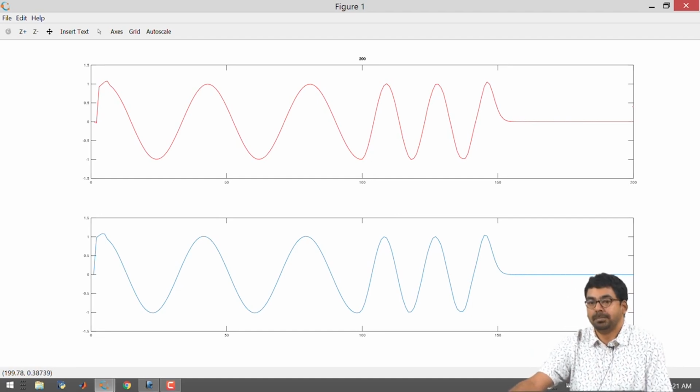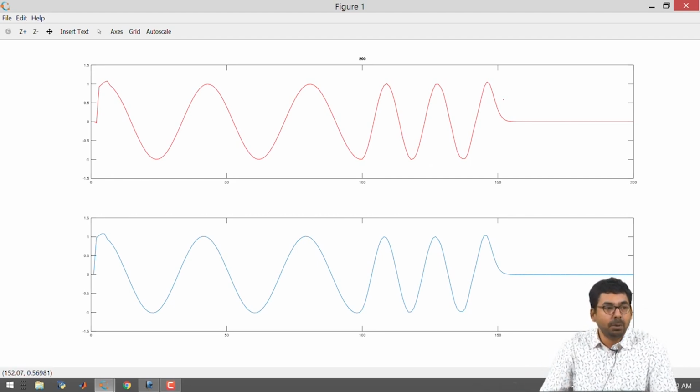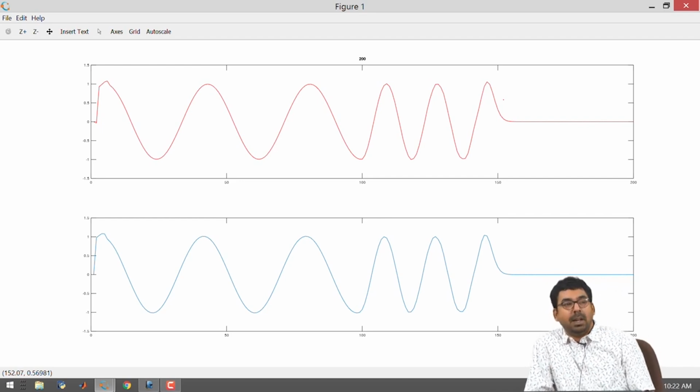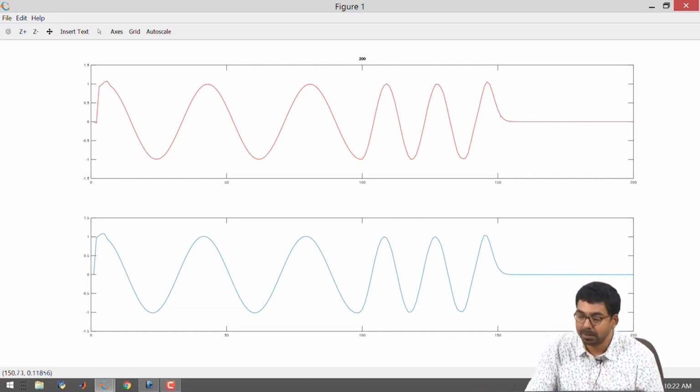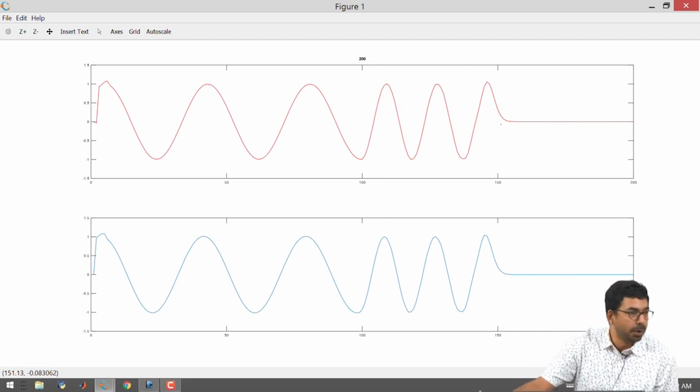It did not do that, simply because we already know that the velocity is going to be 1 by square root LC. So, in the second half of the transmission line, the velocity is reduced. We had L doubling, C doubling, so the velocity reduced to half, and as a result it should have travelled so many time steps. If you look at this carefully, you will figure out that from 100 to 200 is the same transmission line with identical parameters, but it moved only 50% of that. So, it is travelling with about half the velocity.